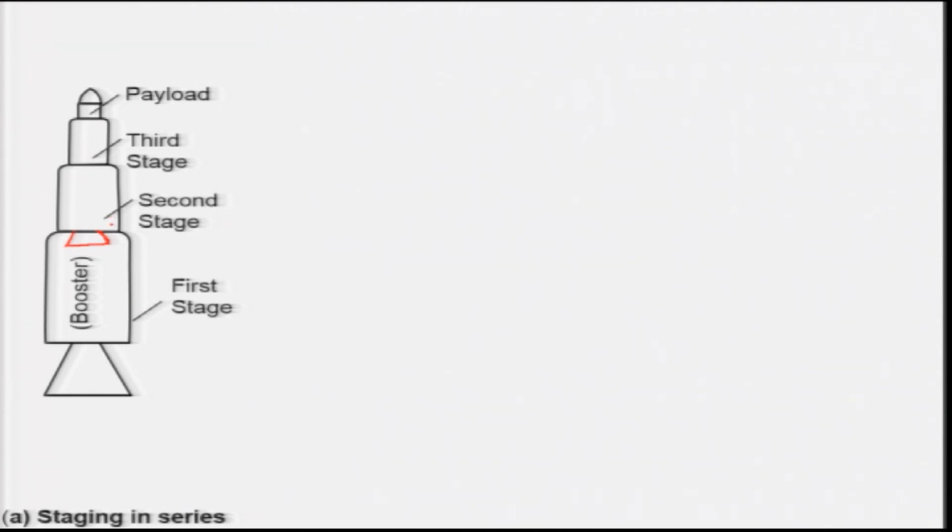And in a similar fashion, the third stage also ignites after the second stage has separated out. Keep in mind that this is a very important one and is used very much, but it is not used alone nowadays. One of the problems faced with stages in series is how the first stage will be separated from the second stage.